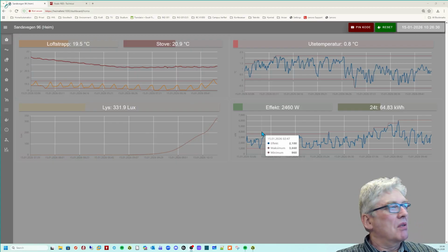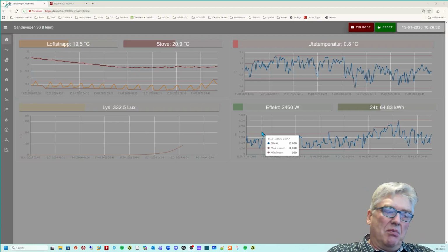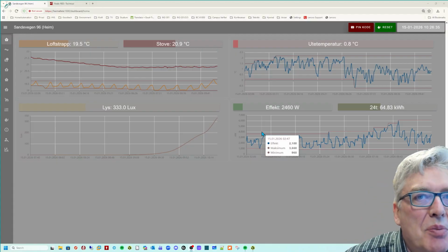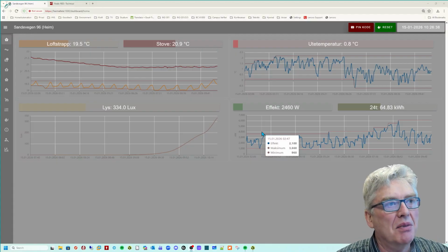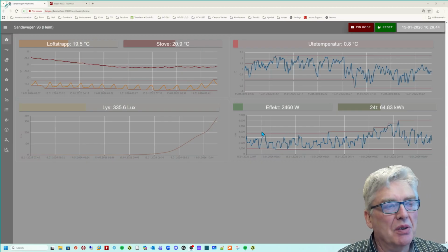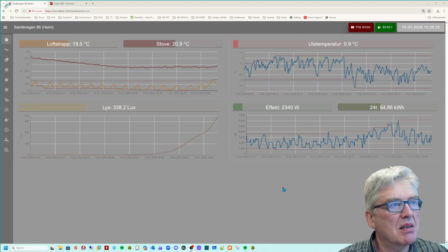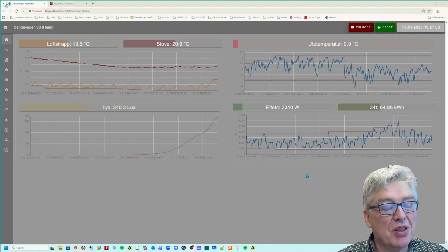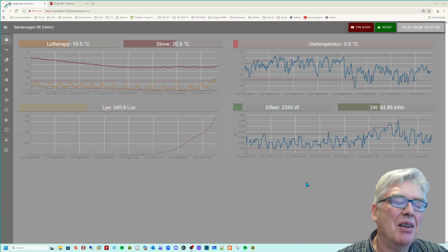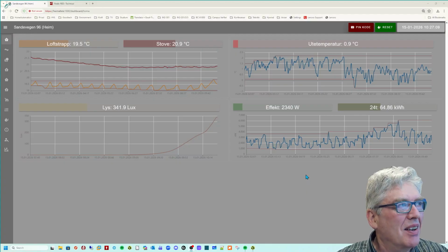What I do is I have an accurate power meter, but what I've done is that here in Norway we have this flash on our meter, and of course you can pick that up with a photoresistor or something like that, and it's 2000 pulses per kilowatt hour. So that's easy enough when you have a control. You just raise a digital input and then accumulate it yourself. So that sensor cost me something like 50 cents. Okay, but the automation is expensive in itself. Not that expensive. Okay, let's go on.